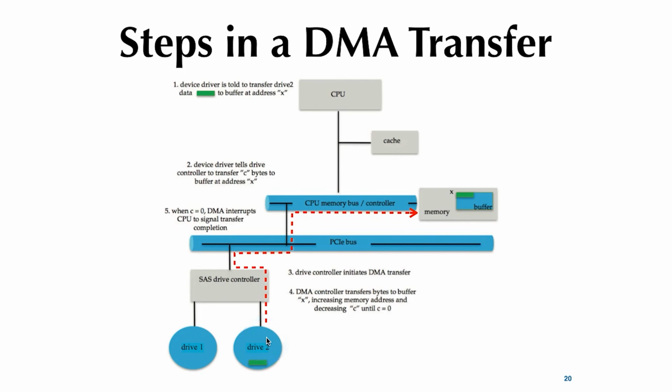So that DMA controller is not part of this drive. It's over here, in the part where it actually interfaces with the memory, okay? It's because it does need to be aware of who needs memory and arbitrate between the CPU and the DMA request. Since it generates an interrupt, you can say, logically speaking, it is outside, but a lot of times it's tightly integrated with the processor and the memory controller.